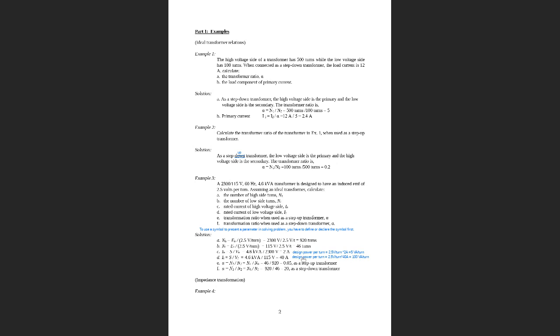But on the secondary side, the low voltage side, there are high currents. So the design power per turn is 2.5 volts per turn times 40 amperes, which is 100 VA per turn. So here a question is raised. Each primary turn suffers a burden of just 5 VA per turn, while on the secondary, the burden on each turn is 100 VA. So the burden on primary and secondary is different.